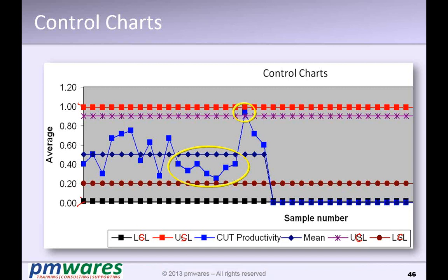The control limits are always tighter than the specification limits. The specification limits are provided by an external party, in many cases the customer. To deliver a quality product to the customer, we set a control limit which is narrower than the specification limit, so that we can maintain the process within the specification limit.